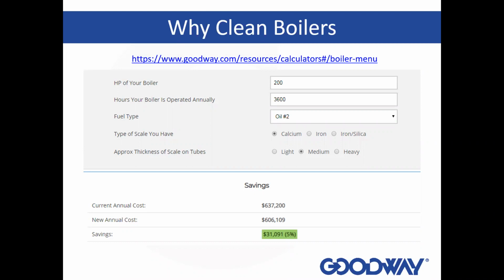Not only do you have the carbon buildup on the fuel side through the tubes, but you have deposition of calcium on the external side of the tube. So you're creating an insulation barrier on both sides. So it's always a good practice with a fire tube boiler to descale the water side, or get a vacuum setback on the fire side of the fire tubes.